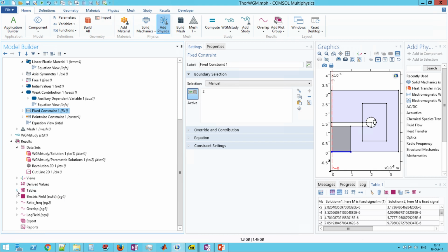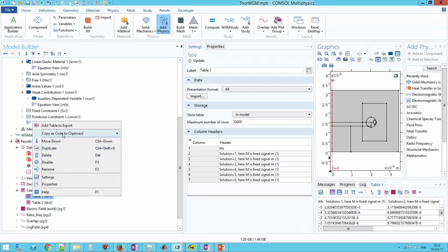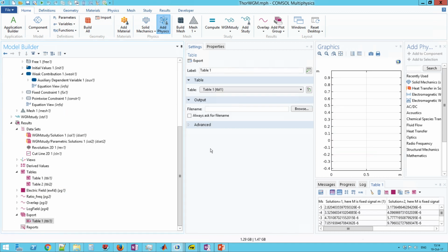Well, I usually try to separate things, so I get some table, then I add a table export, give it a file name, and it doesn't include the header, and it just gives me the table as text, and then I import it to MATLAB. It has just a one-word function to get the data from the text file, so it is quite easy.